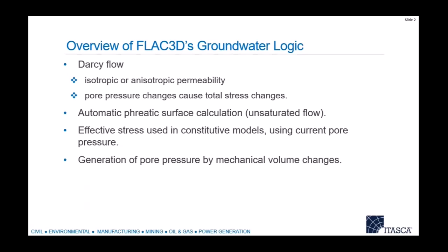Let's look at FLAC2D's groundwater logic, the fluid logic. Called Darcy flow. It's not a full CFD code in any way. It's just straight up Darcy flow. We can do isotropic or anisotropic permeability, basically whether you give a scalar or a tensor. And we do have both one-way and two-way coupling between the mechanical and the fluid logic. And I'll talk more about details about that later.